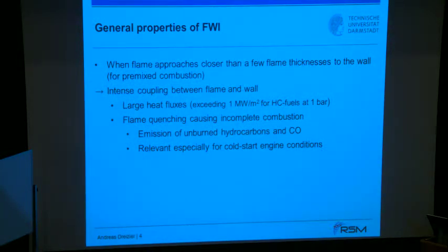For hydrocarbon-based fuels like methane, at 1 atmosphere, you have up to a megawatt per square meter. That's a huge impact upon, of course, the chemical kinetics, such that the flame is then quenched, and that means you have incomplete combustion. If you have incomplete combustion, then you have unburned hydrocarbons, and you're oxidizing the CO not completely to CO2, and that is, as I said, specifically important for cold start engine conditions where as well the three-way catalyst may not have been ready for operation. So that makes up a lot of the emissions that we still have in the IC engines.